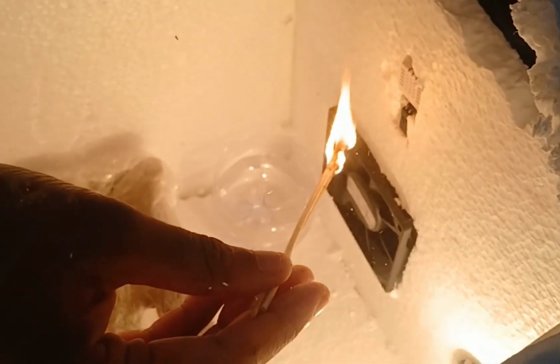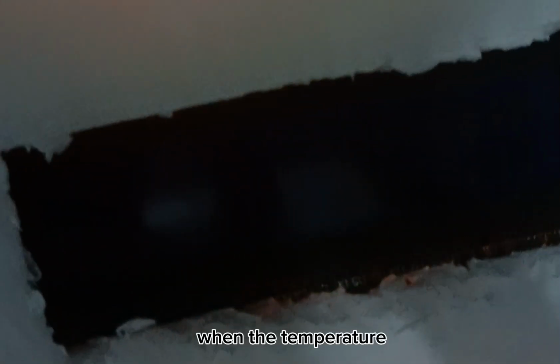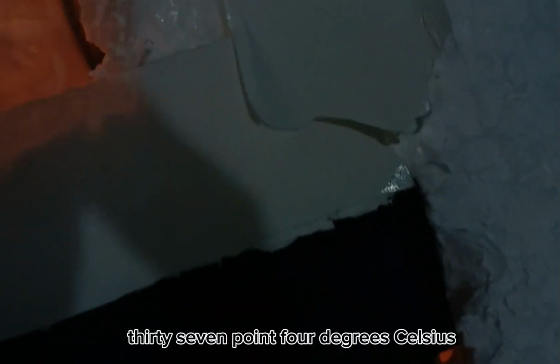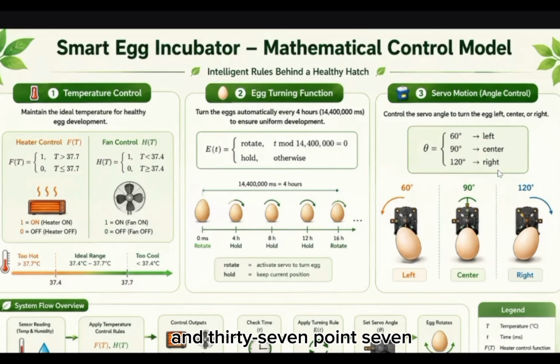When the temperature becomes higher than 37.7 degrees Celsius, the cooling fan turns on and the heater turns off to reduce excess heat. When the temperature drops below 37.4 degrees Celsius, the heater turns on while the fan turns off to increase the temperature. This helps maintain a stable incubation range between 37.4 and 37.7 degrees Celsius.